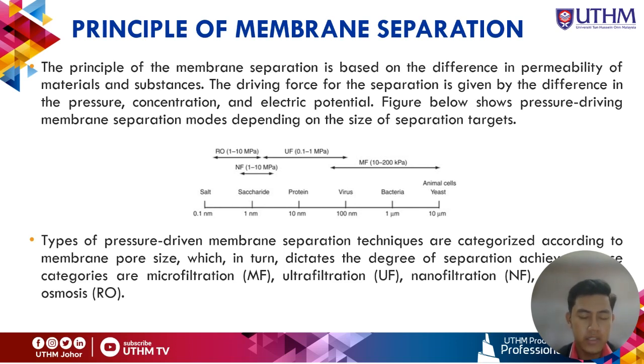The types of pressure driven membrane separation techniques are categorized according to membrane pore size, which in turn dictates the degree of separation achieved. The categories are microfiltration, ultrafiltration, nanofiltration, and reverse osmosis.